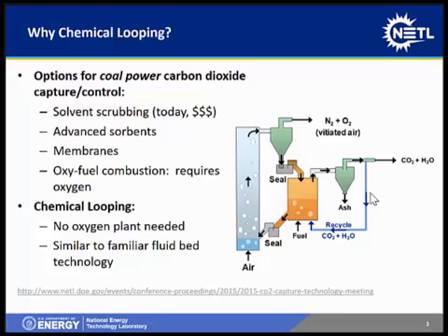The interesting thing about the chemical looping system is that it doesn't require separation of oxygen or the use of complex schemes for separating carbon dioxide from other components of the exhaust. Now, one of the key things about this type of combustion system is that we have particles which are being transported by a flow of gas, and those particles are what carries the oxygen from one place to another. And flow of those particles is clearly an important aspect of designing and understanding such a system.